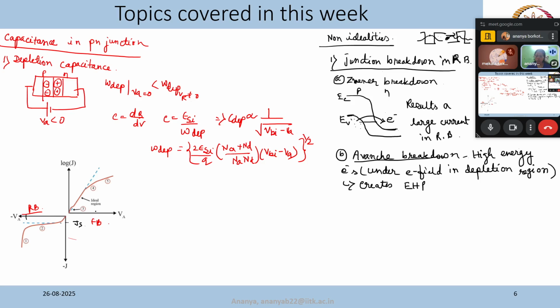This is reason 2, and reason 3 is this: in all our assumptions we are considering no recombination and generation in the depletion region while deriving the current in the forward bias, but there will be some recombination and generation, especially at lower voltages. So reason 3 reflects this.